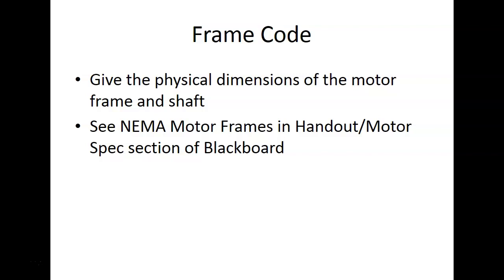So now these plugs that we have against the wall are NEMA 5-15, which means it was a 15 amp plug. A NEMA 5-20 would be a 20 amp plug. So they standardized that, and now I can go to Lowe's and buy a cord.